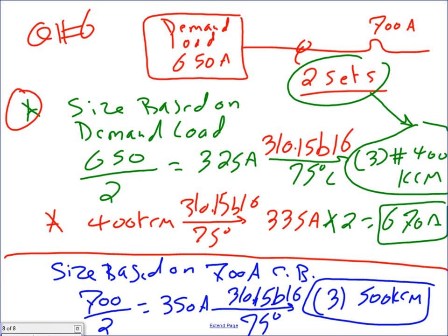There are 2 ways, guys, to size a conductor. You can size it based on a load or based on the overcurrent protection device. The best way, if it's non-motor, is to size based on the overcurrent protection device, especially for panels. Always the best way. Now, up to 800 amps, if you know your load, they allow you to go 1 step lower. After 800 amps, say 1000 amps, forget about everything else. The breaker will rule after higher than 800 amps.